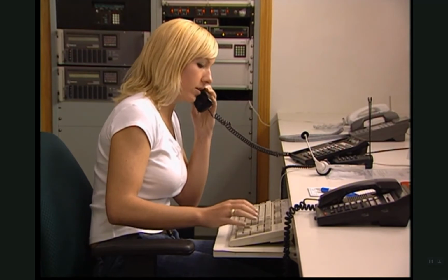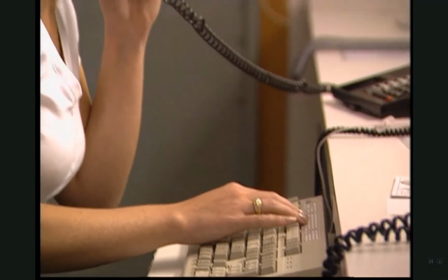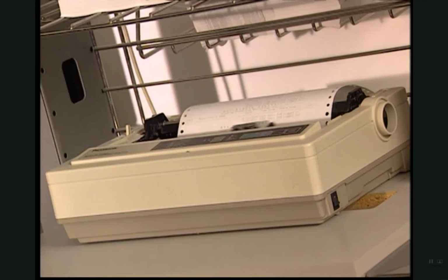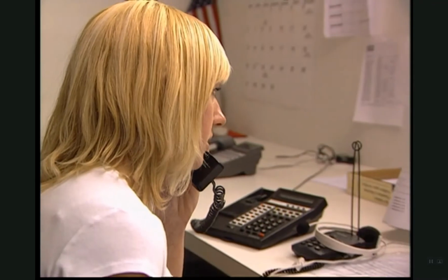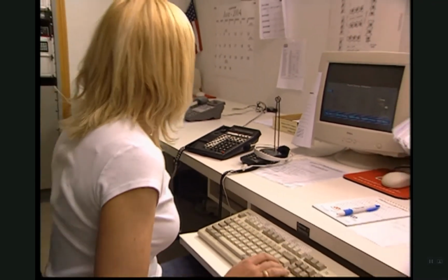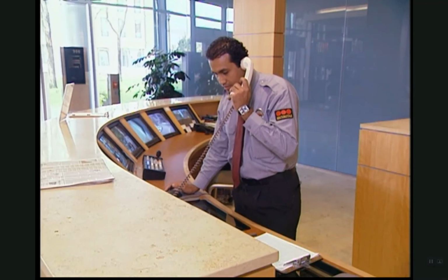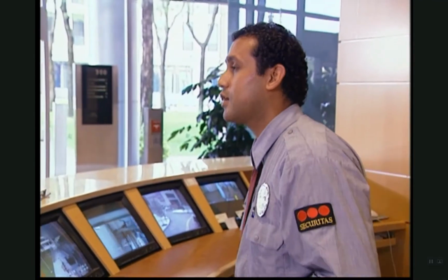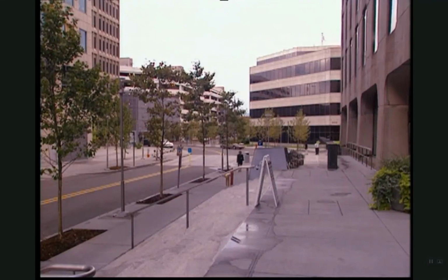A supervising station is a facility which monitors for alarms, as well as supervisory and trouble signals, retransmits the signals to a fire department, notifies responsible personnel about supervisory or trouble signals, and keeps records and creates reports. A property owner may establish a proprietary supervising station to handle alarm and supervisory signals from their own properties. These are often found at multi-building facilities such as schools and manufacturing campuses.